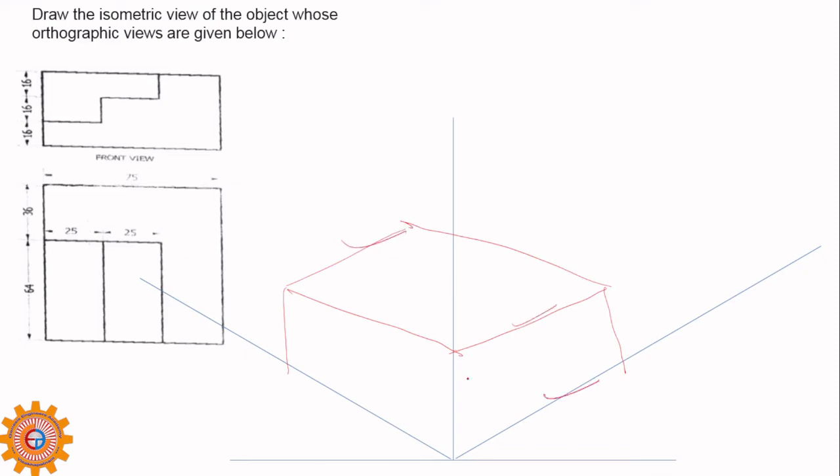If you clearly observe this line parallel, and this line are parallel. They have to be parallel. Okay, so this line and this line. Okay, so vertical lines are parallel to this, and this other sides are, one side is parallel to this, the other sides are parallel to this. If it looks like a rectangle, you have to draw as a parallelogram. Okay, so to draw that one, so I draw the front view first.